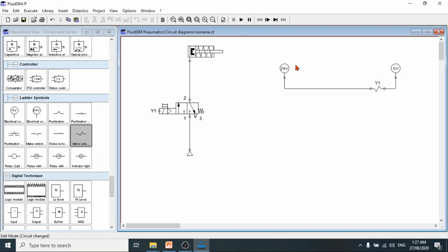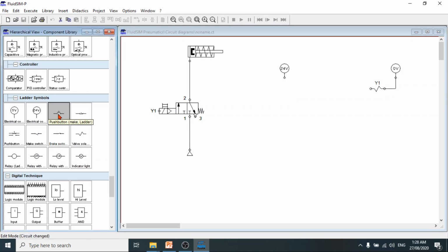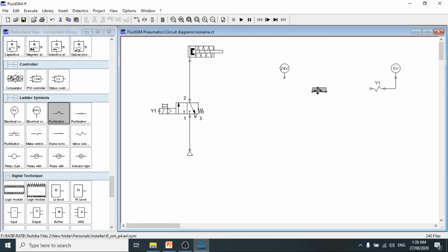So in this case, we'll find a way wherein if we trigger that particular element, it will enable this solenoid coil to be energized. And whose element is that? Okay, so the answer is the normally open push button. Take note, normally open will make contact, so that it will enable the solenoid coil to be connected to the power supply.